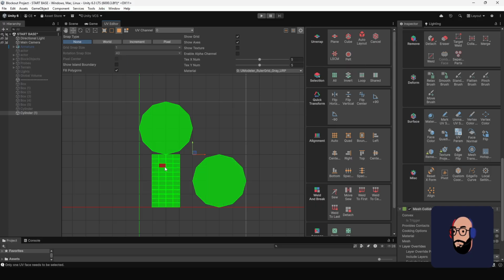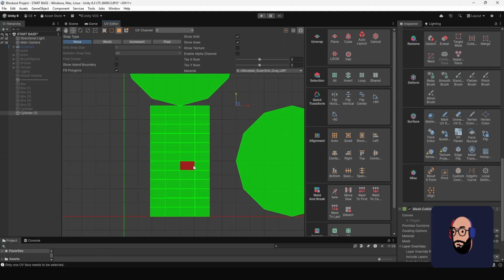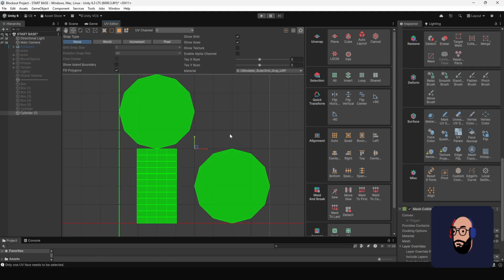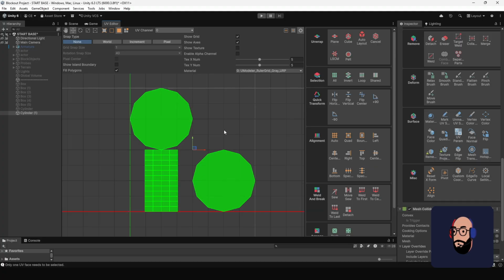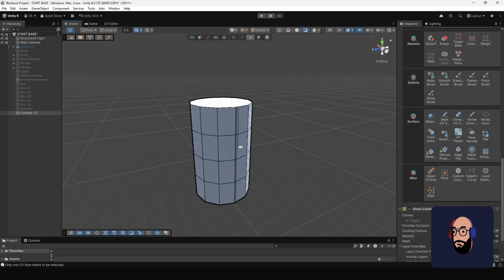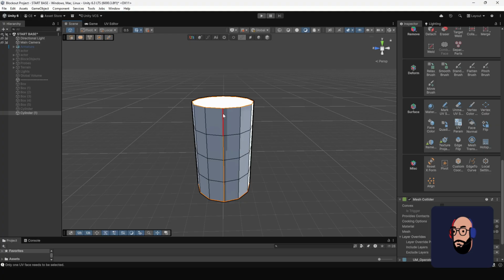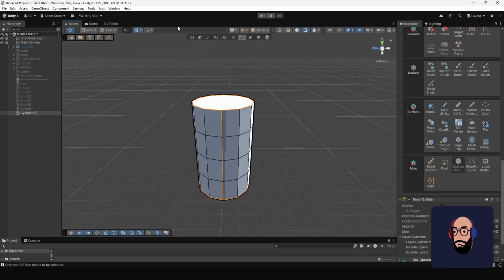And if you noticed, now it's perfectly lined up exactly the way that we would expect it to be, and it looks really good. So that's a very, very good way to utilize the LSCM. And what's great about this is that it works really well when you're working on characters. So imagine this is like the arm of a character and you wanted to unwrap that arm properly. In this case, you would create maybe a seam in a certain place so that you can completely unwrap that character arm and you can do your texturing that way. So that's a very useful tool.